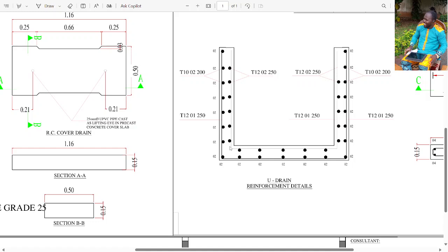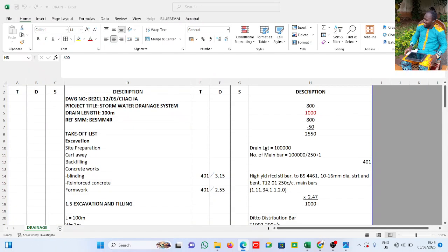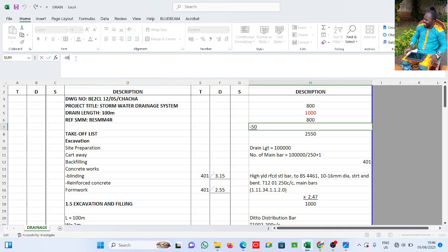And of course this is inside. See this itself, 1 meter from here to here. This is even extending small. I will account for it, otherwise I'll be short paying myself. All right, so this is what we have here. Okay, this is it. This is 800, 1 meter, 800. Now if you look from the drawing, I have to less cover to see the reinforcement. This has to be 3 covers, 25, 25, 25, which is 75.